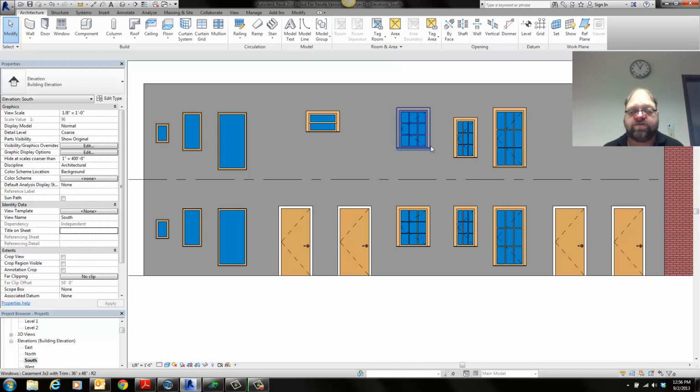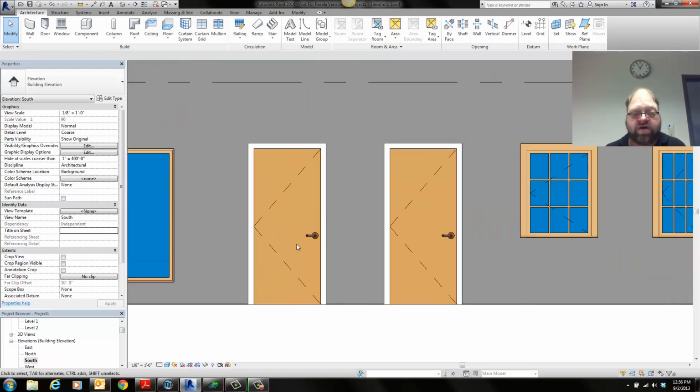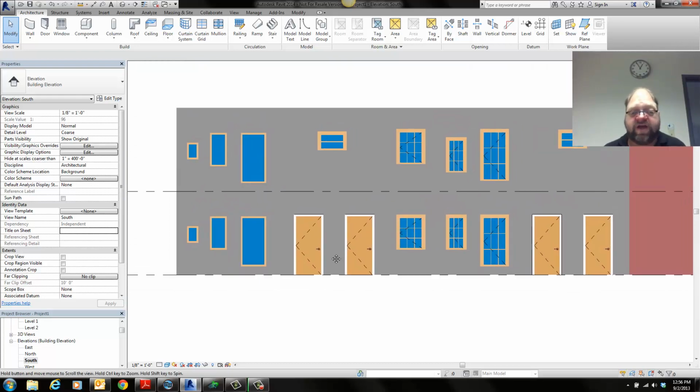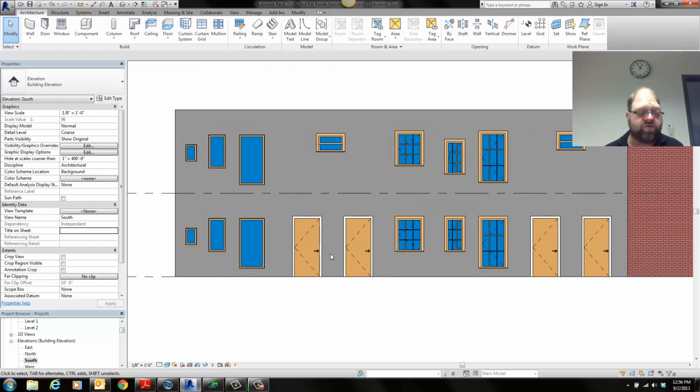Or I was changing the material property, which is another way you can affect the behavior of the family. Or in the case of the door handle, I was describing which family it's going to use as a parameter. So parameters affect the behavior or the relationships of the elements within the family. They are ways to control what we're seeing.